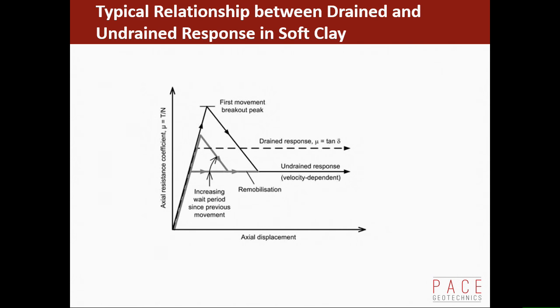If you have a drained response, if you have a sandy seabed, it's much, much easier because you tend to get that sort of response. It mobilises itself and then starts to slide, and the friction is fairly well defined. So it's a much easier type scenario to understand.